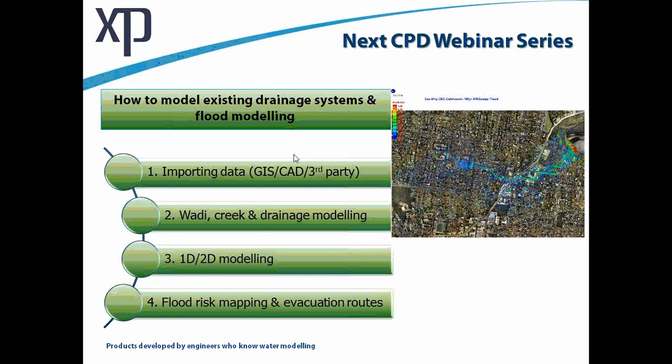And this is what I'm showing on the right-hand side, a video of flooding. So I want to link the flow conveyance, the existing flow conveyance network, the drainage systems, and that could be the wadi with the pipe network as 1D, and get the flow running through those, and then create flooding for those extreme events, and show the interaction between the 1D and the 2D, but with modeling software rather than design software.